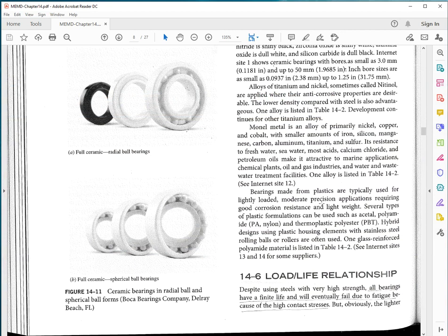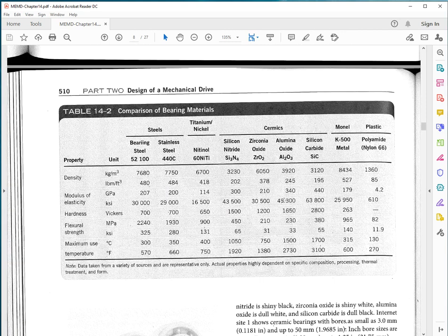That's a fact, and there are various mechanisms of failures of the races of the rolling elements. And again, when you have electric discharges, stray currents, you could prevent those from happening by using non-conductive rolling elements, at least, if not the full bearing. Okay.